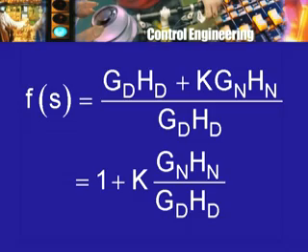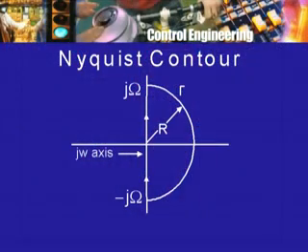With this in mind, now we can choose a contour, and this was of course the contribution of Nyquist and Barkhausen, that is, they chose a contour which will do the job, and the contour is this one. Remember, it has to be a simple closed curve, but it has to be such that it will be useful to us. So, this will be the contour. Choose a part of the j omega axis, and we can choose it in a symmetric fashion. So, let us say an upper limit here is j capital omega. This omega is not to be confused with speed, it is just some real number. Of course, we will interpret it as frequency, as you will see.